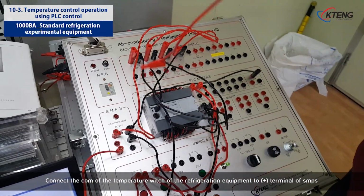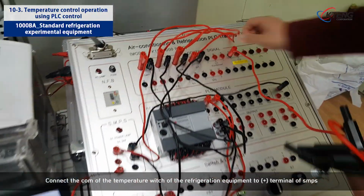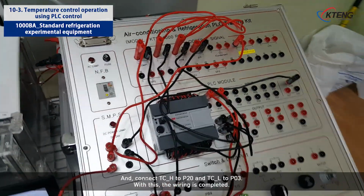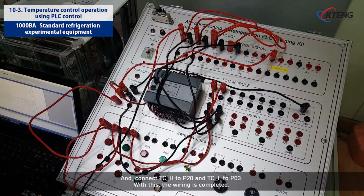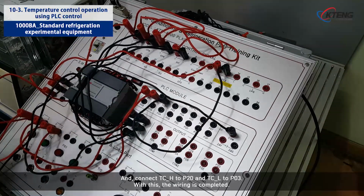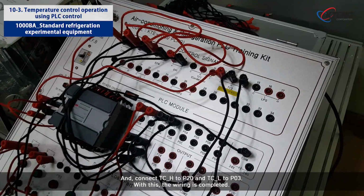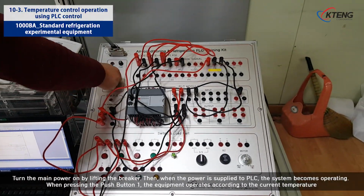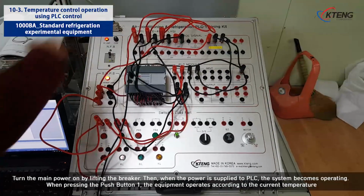Connect the COM of the temperature with the refrigeration equipment to positive terminal of SMPS and connect TCH to P02 and TCL to P03. With this, the wiring is completed. Turn the main power on by lifting the breaker. Then, when the power is supplied to PLC, the system becomes operating.